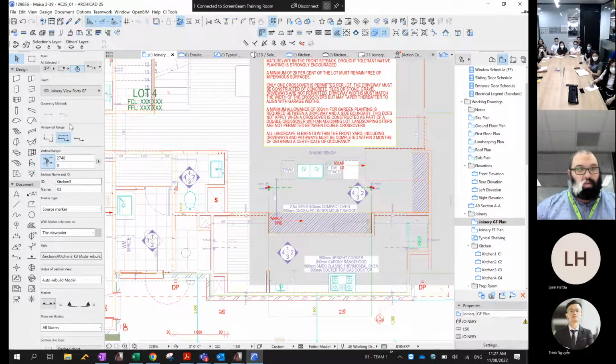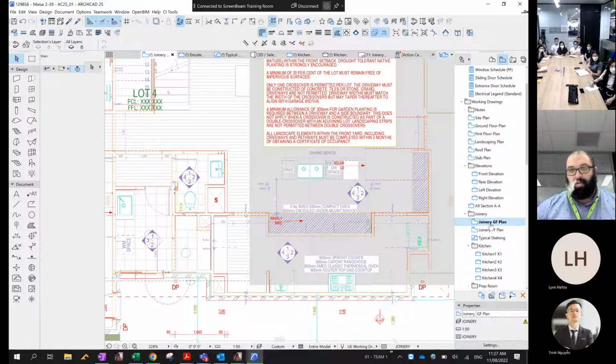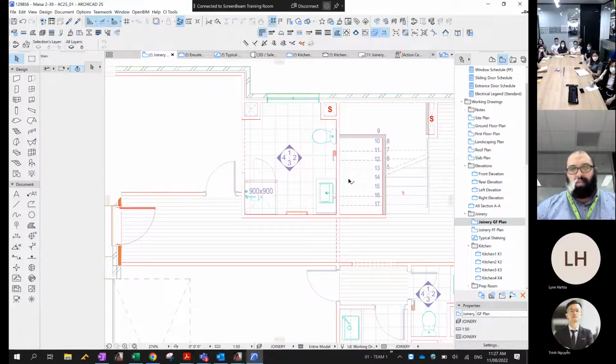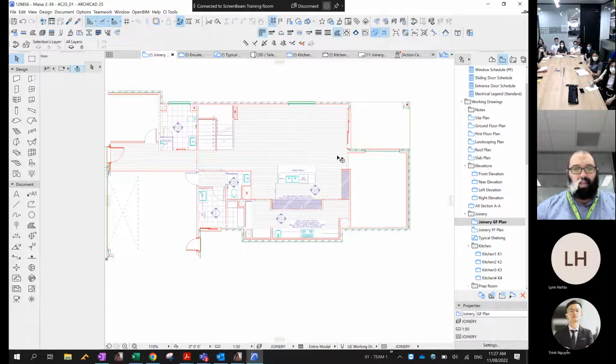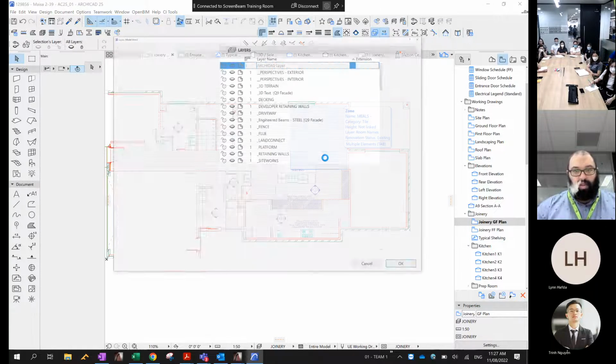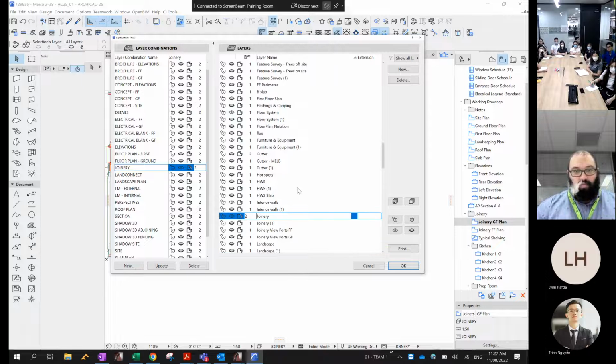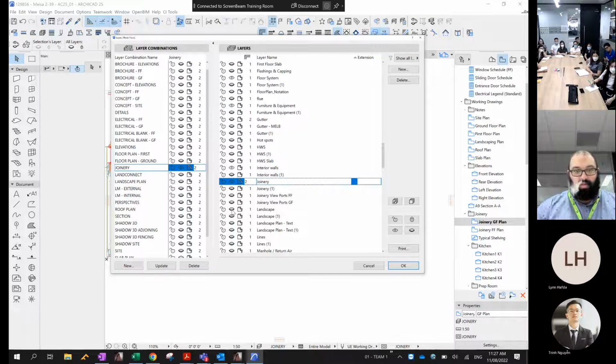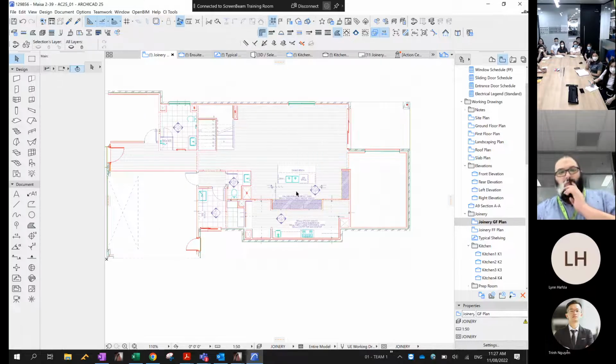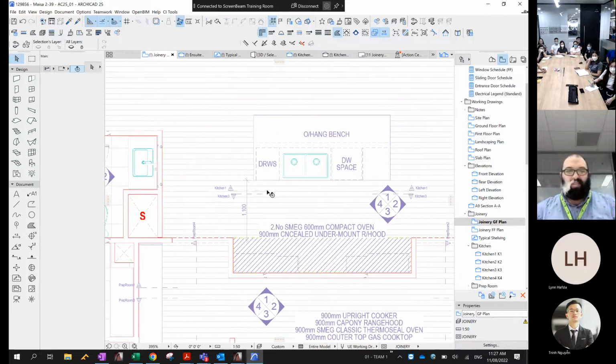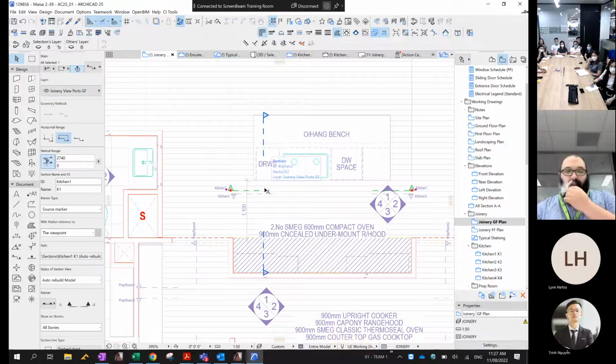This is put on the Joinery viewports ground floor. Perfect. So you'll find some of the older masters will have it set on the sections elevations layer. The newer ones, like this one here, will be on the Joinery viewport elevations ground floor. Turn that on. At the moment, the current masters are set up using section markers for the joinery. We'll continue that method for now until the brand new version of the masters is released, where it's been fully set up using internal elevation markers correctly.